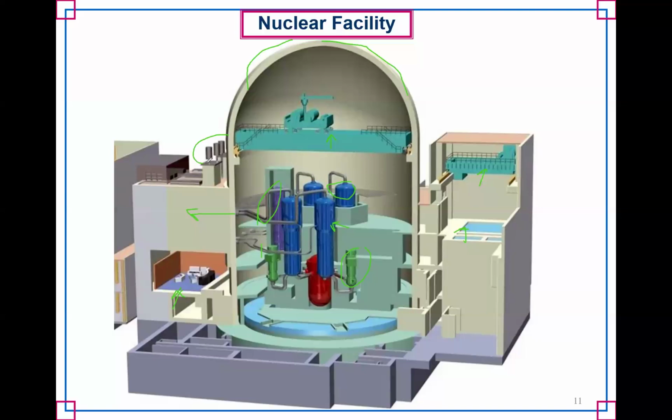And then over here, you have some pressure relief valves. If for some reason you have a problem and you have all the steam and you can't send it to the generator, you have a lot of heat. So you have to just dump that to the environment to get it to cool down. And again, that's not a problem because in a pressurized water reactor, it's not contaminated. The steam generators separate the primary, which is the loop that actually does come into contact with the nuclear fuel, and the secondary, which is the water or the steam that goes over to the turbine generators and the condenser. So there's a physical barrier between the two, so no radiation should get out from the primary into that secondary material.